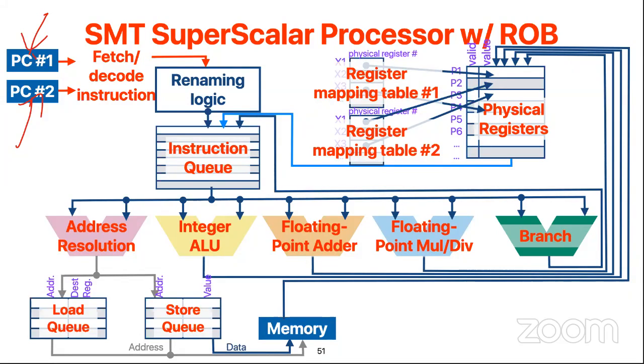And you just need two register renaming tables so that you know where the architectural registers of program 1 are now. That's all you need to support simultaneous multithreading. On average, it takes less than 5% of the die area, but you get the benefit of using the unutilized part of your pipeline.